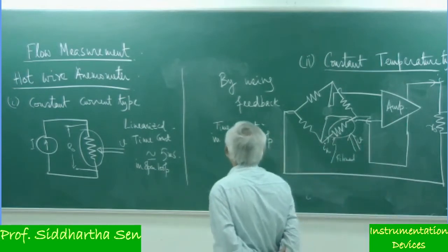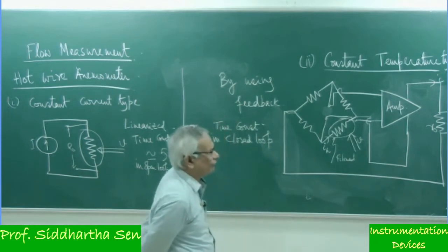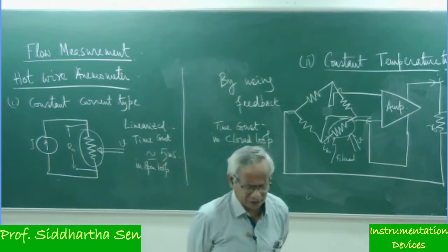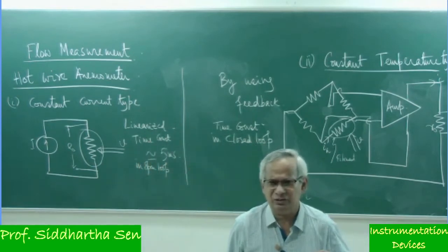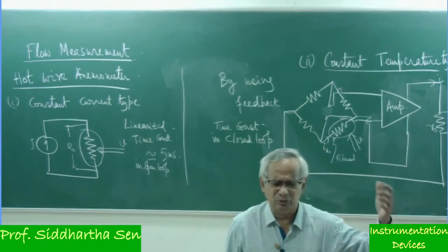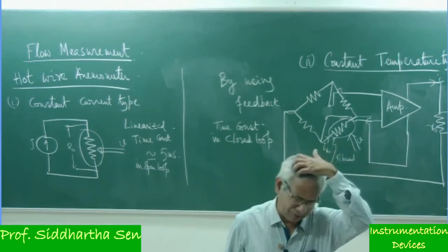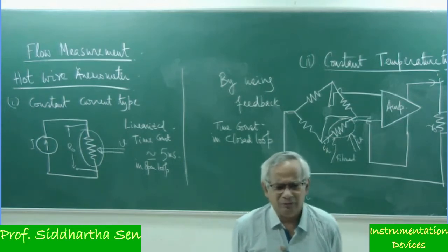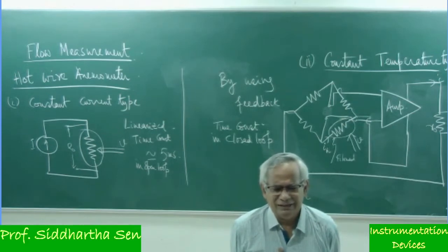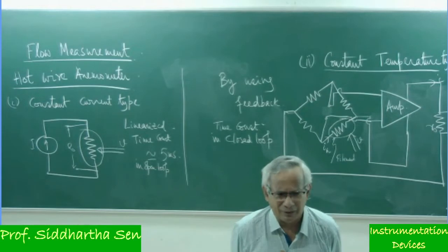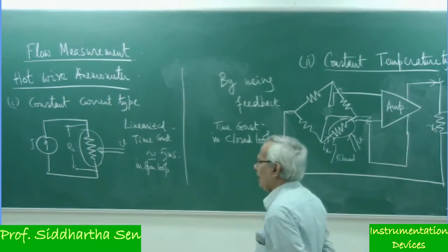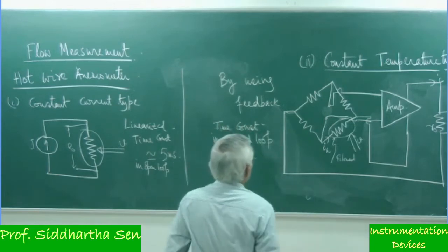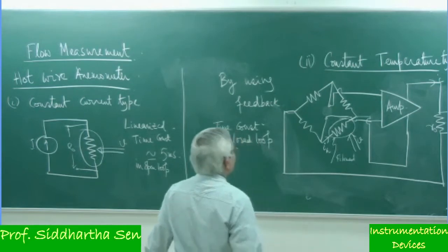If we recall the effect of feedback in any system, if we recall the first lectures in control theory, or you can go through Ogata or Kuo's very classical books, you can see that one of the effects of feedback is a decrease in gain and an increase in bandwidth. If the bandwidth is increased, it means the effective time constant decreases.